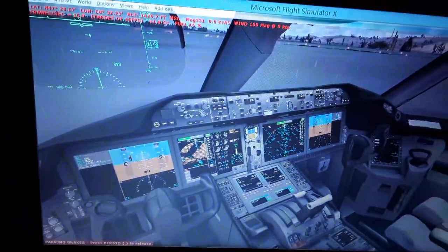So we will receive from the onboard antennas of the aircraft the radio frequency and display the horizontal localizer and vertical angle of approach for the LSZH localizer, the instrument system of the airport. We have the LSZH localizer crossbars also displayed in the primary flight display, and the flight director crossbars for manual guidance of the aircraft, and the autopilot crossbars for automatic guidance of the aircraft.